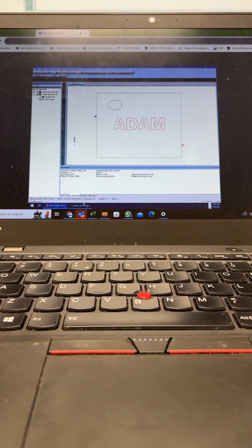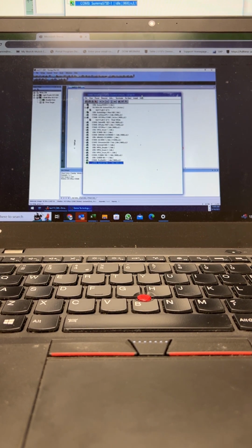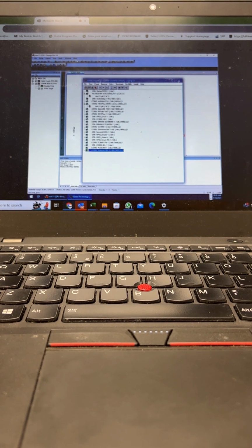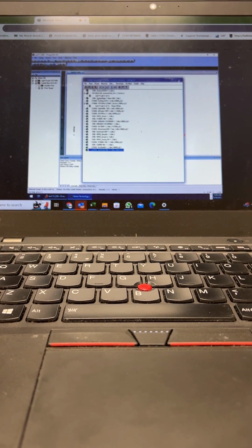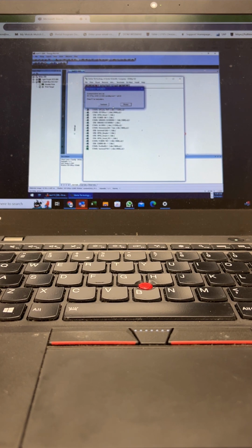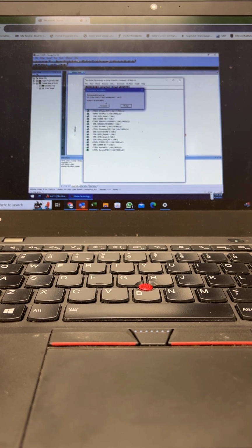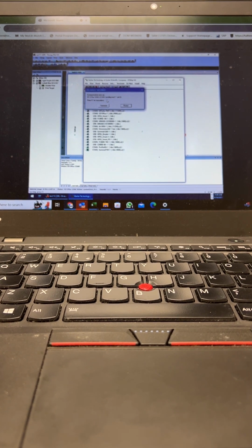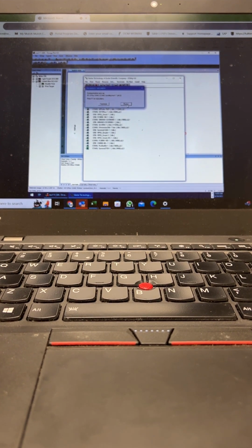And when you click on the print and the cut, it will open up a third program, which is our Queue Manager, and that is called Gerber GQ MGR. This will show all of your devices and any jobs being output to them. I currently do not have my plotter turned on, so it is giving me a communication error. And it gives me the option to terminate or restart.